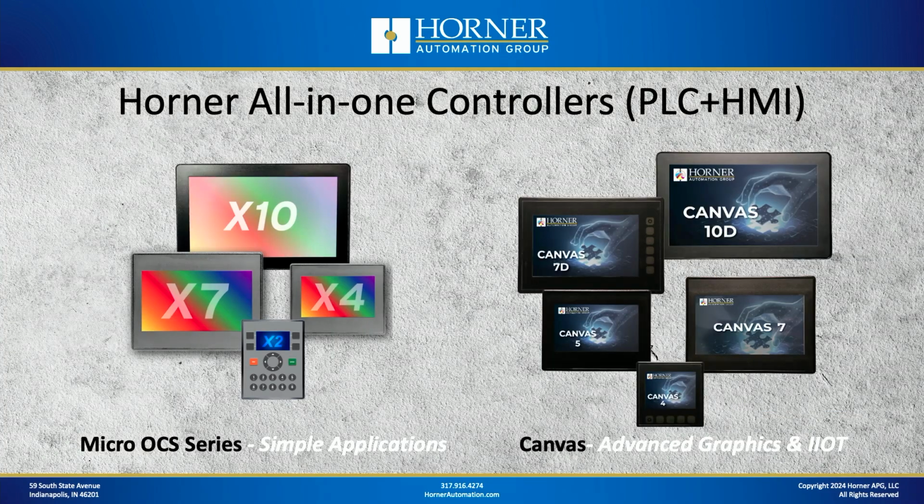Okay, so let's quickly compare Canvas and the Micro OCS. The Micro OCS is our entry-level all-in-one controller. It's great for simple applications, which includes a lot of stuff. With Canvas, you just get more advanced capabilities. You get more memory, the ability to support larger programs, the ability to have faster scan rates. You have more graphics tools available to you. You have more protocols built in.